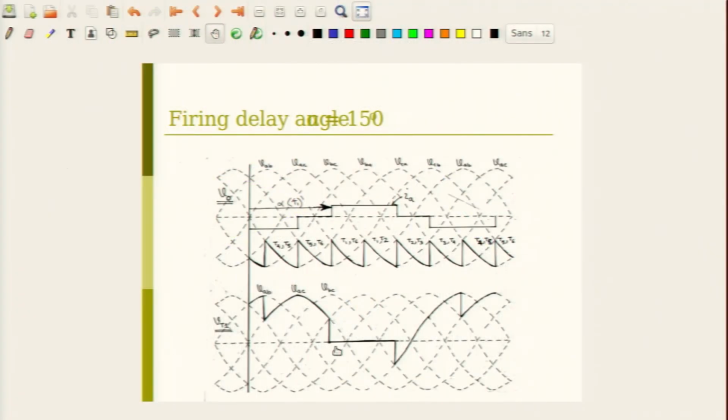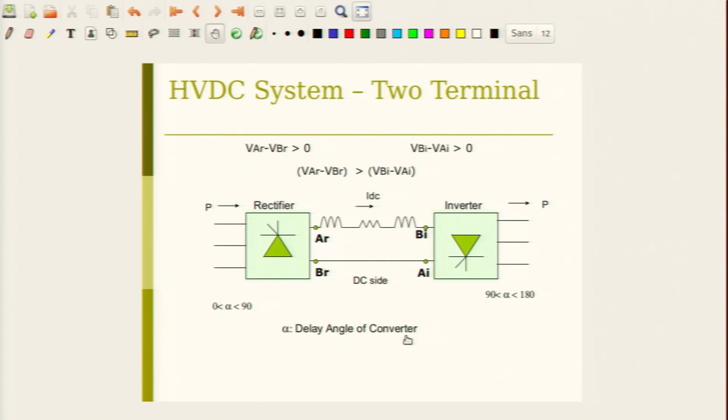And the voltage across each valve has this waveform. It is forward biased at this point, and you have a current flow. This is the point at which the device is switched on, the voltage across the device becomes 0, and when it is switched off again the voltage is negative for a short while, but only for a short while, unlike a rectifier.